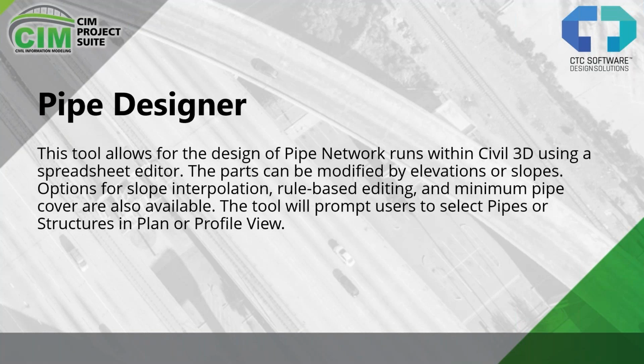This tool allows us to design pipe network runs within Civil 3D using a spreadsheet editor. Parts can be modified by elevations and slopes, with options for slope interpolation. Rule-based editing and minimum pipe cover are also available. The tool will prompt the user to select pipes and structures in plan or profile.